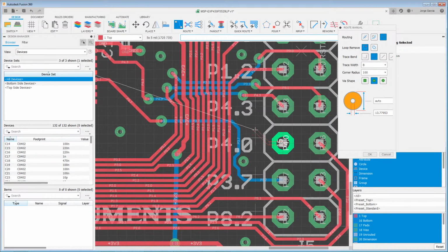So, if you hold Shift and middle click, you'll see that you can change what the starting layer is. So Shift middle click, I can go from top to bottom at the beginning. Okay, very important function. Shift middle click. I'm going to backspace again. Shift middle click. Now I'm on the top. I started as if I were on the top. Shift middle click. Started as if I were on the bottom. Okay. Something that comes up a lot and is not super well known. Okay, so it's something you want to keep in mind.